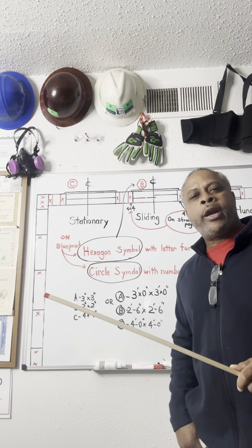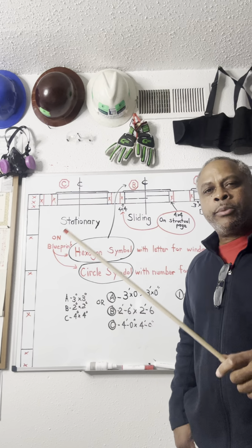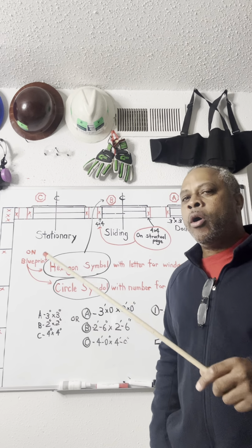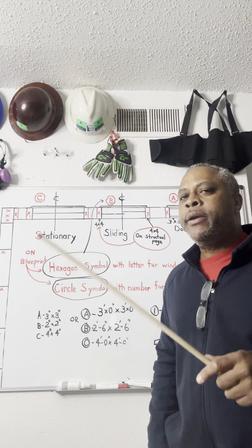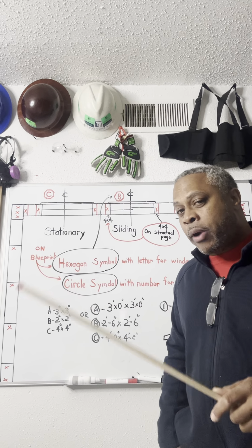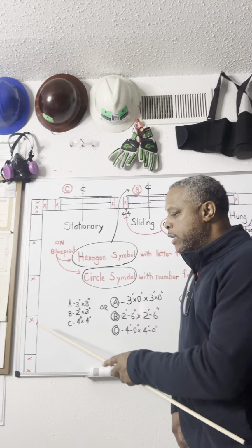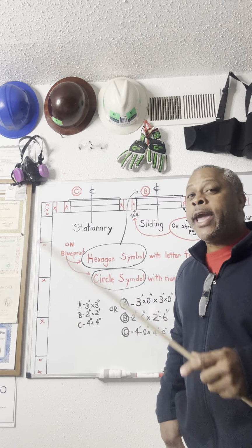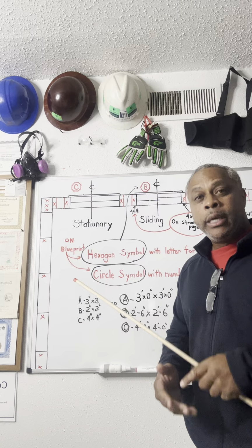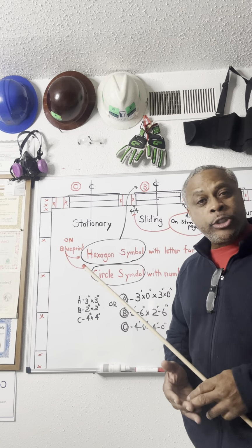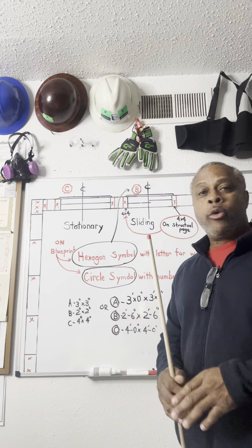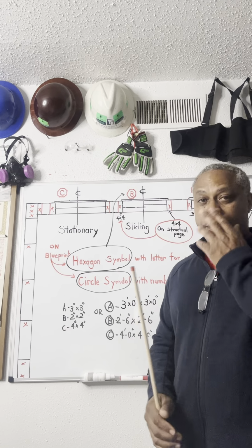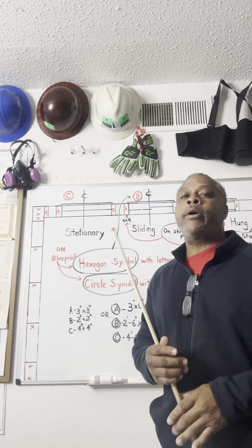Our miniaturized framing project that we do have that's going to be shown to you, stay tuned, it's going to have layout marks. All the plating for every wall on this project is going to have stud markings. Also, we're going to have the windows, the headers, the cripples for the tops, the bottom cripples, the window seals if it's a window. Doors don't have bottom cripples or bottom seals. They just have top cripples.